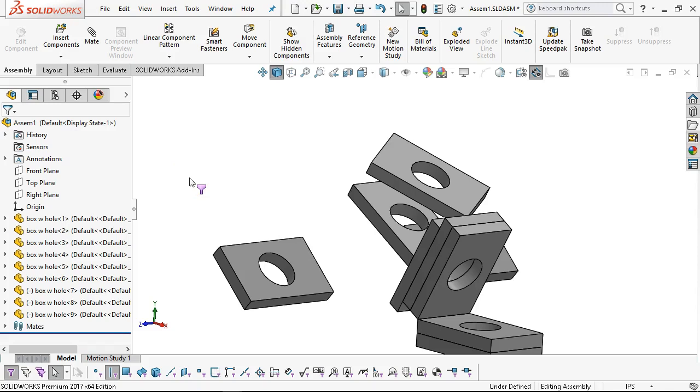I have a little funnel, and it automatically went to edge, E. So if you're on the keyboard and you accidentally all of a sudden can only select edges, none of the faces, none of the points, none of the vertices, none of our geometry, it's because you have a little funnel on your screen and the E key, and there was another one that shows up as well that will select or deselect for edges.